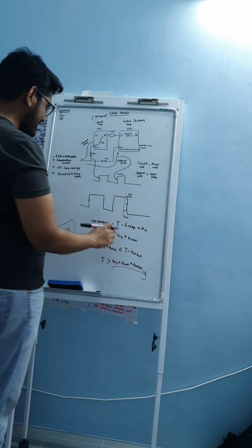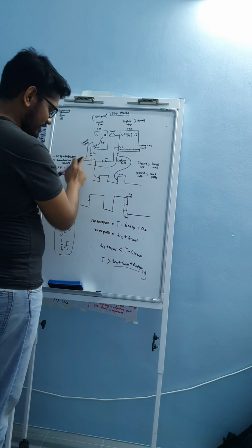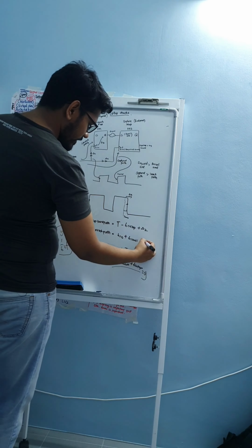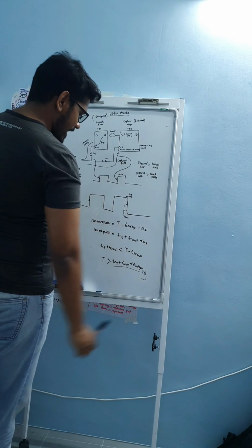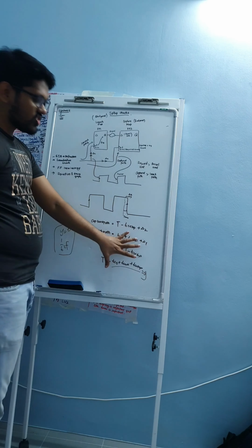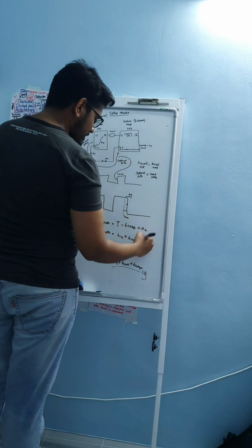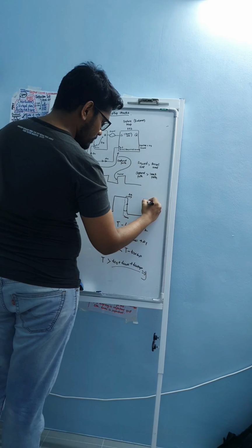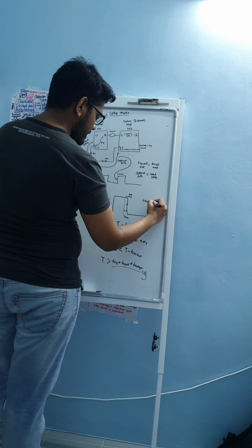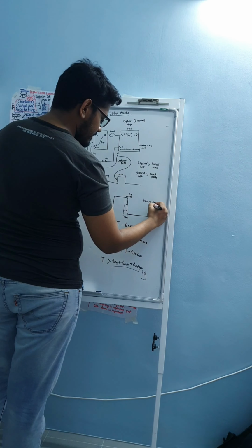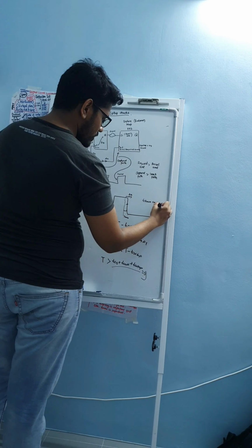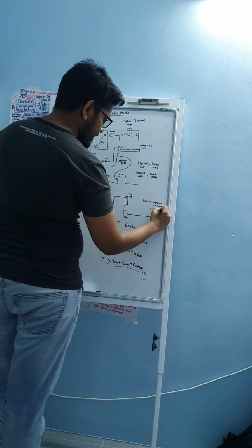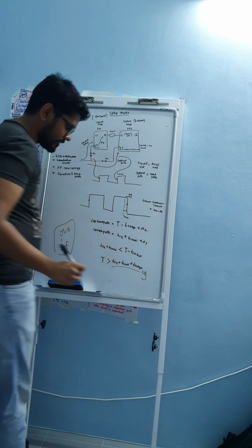That's so simple. Then at the same time, we're going to add delta 1 over here. And then you can actually say it's your T skew. Immediately this is considered as T skew. Your T skew is your captured minus your launch, which you would get delta 2 minus delta 1.